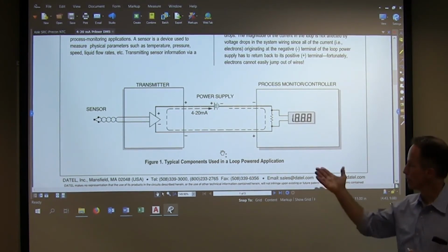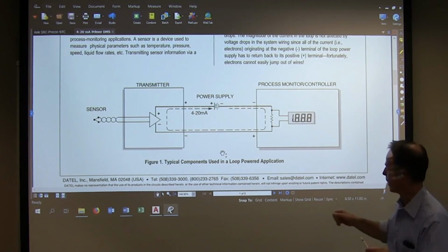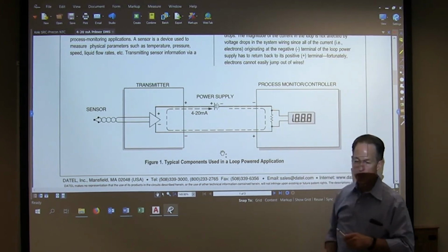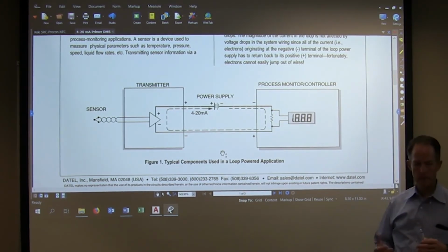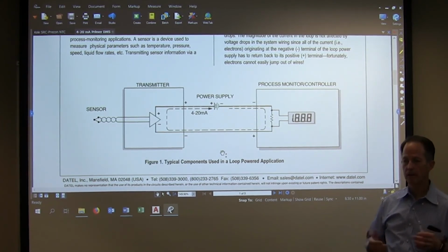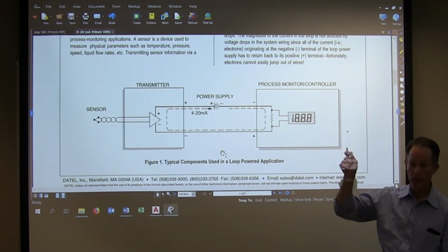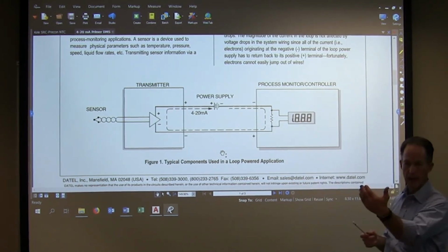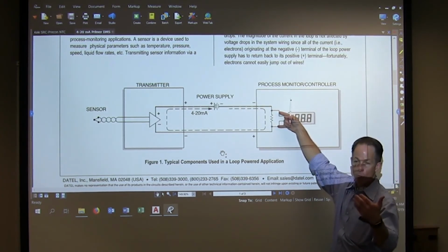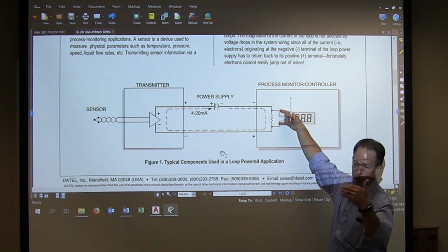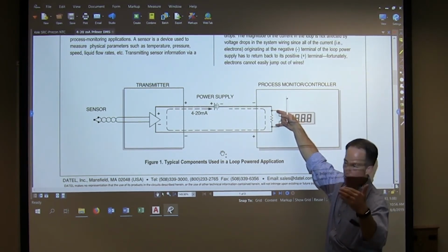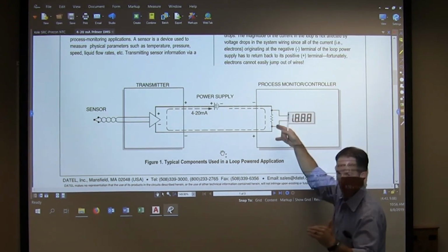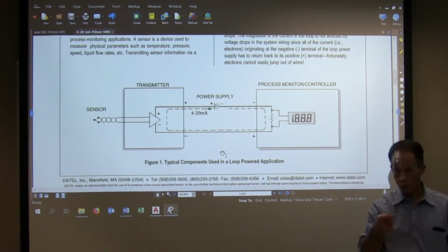So you're like, I should be at 20 milliamps. And I go and put my meter, say I can get to that resistor, across there, and I'm reading 16 or 17 volts. You're like, well, that doesn't make sense. Why am I reading that? Because I should be all the way to 20 milliamps or 10 volts. Okay, so the way that you do that then is you back it down and you keep your meter here. And what will happen is your meter will stay at 16 or 17, whatever it was, it'll stay at 17 volts. You keep backing down the sensor, and then all of a sudden, it no longer will say 17, it'll start to come down. Okay, and that's one way to troubleshoot it.